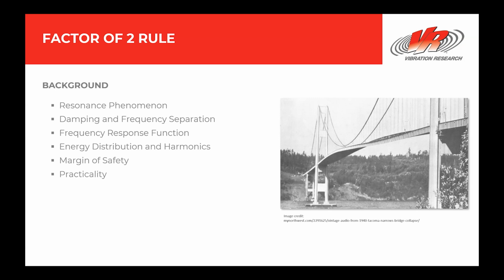Resonance occurs when a system's natural frequency matches the frequency of external vibrations or forcing functions. This leads to maximum energy transfer between the environment and the product, resulting in large oscillations and excessively high stress amplitudes. With nowhere for the energy to go, fatigue accumulates rapidly and the product fails.